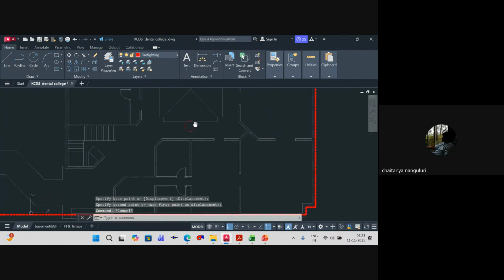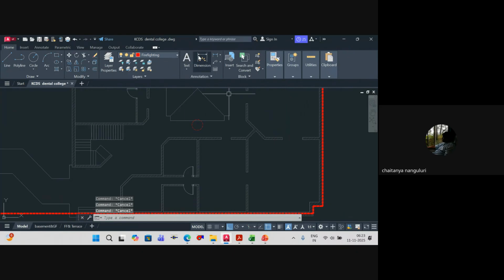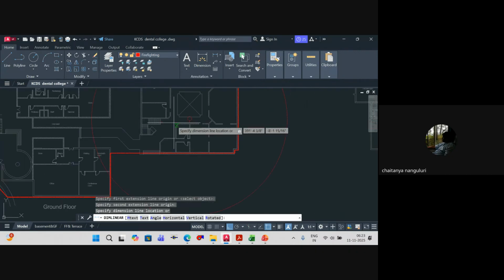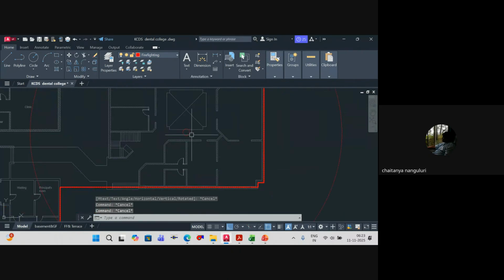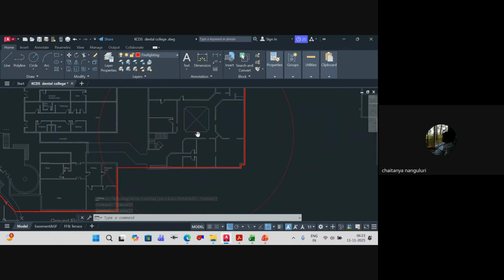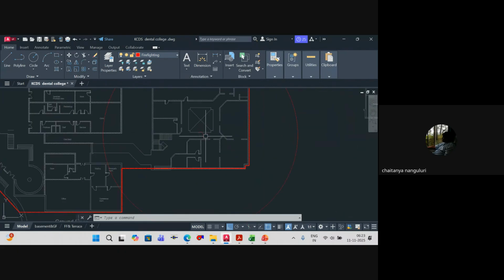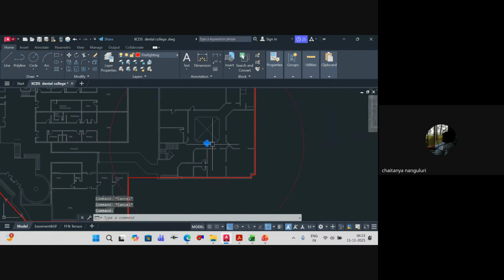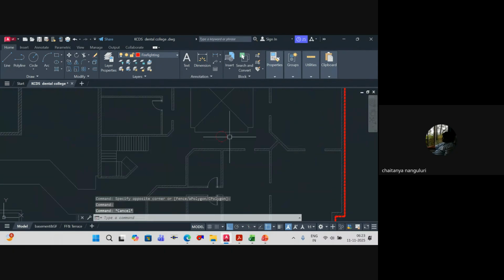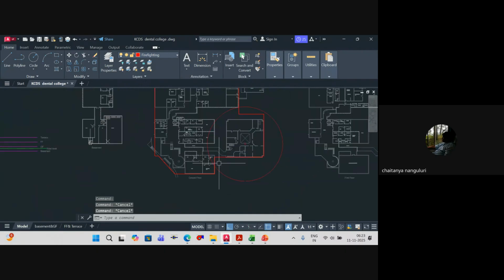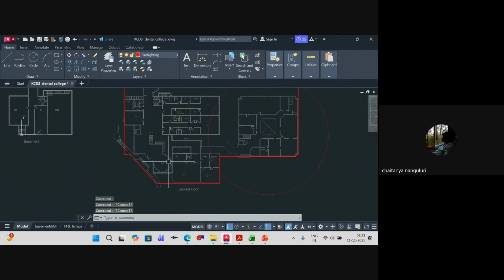This area, I'll take one number. It should be near to your exit, but anyway, not much distance is there from the exit, so that's okay. From your fire exit, it's hardly 27 feet. Not a problem. Generally, we say 5 meters, that is 15 feet, but it's a very minor deviation. Or if I don't want to deviate, one I have to place it over here, one hydrant over here. It's again how much risk you want to take. This is the first location.